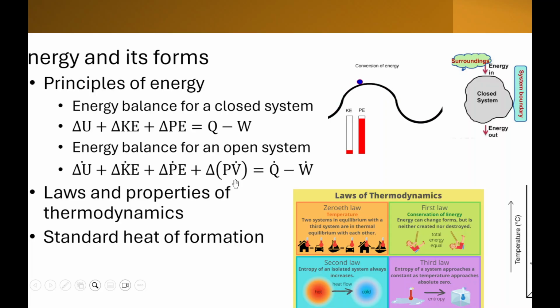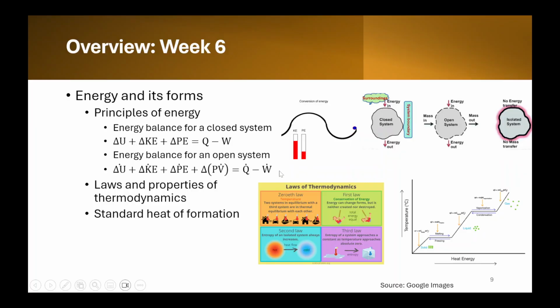This is the volumetric flow rate. Basically, there will be some pressure exerted by the fluid or the component. So that change is equal to Q dot, the rate of heat in, minus the rate of work done by the system. This is basically known as shaft work. So W dot is basically W dot flow plus W dot S. This term is your flow work.